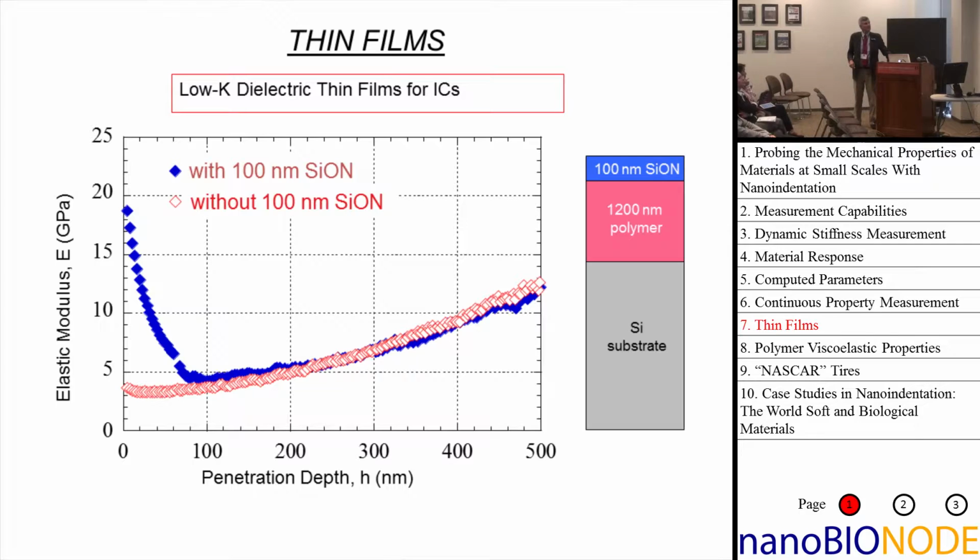I thought this stuff might be interesting. So would 18 gigapascals be the actual property of S? This one? No, because you haven't. In order for me to be convinced that 18 is the number up there, I'd have to see this thing plateauing out at some value, and we didn't get there. Okay, so that was too thin to measure.